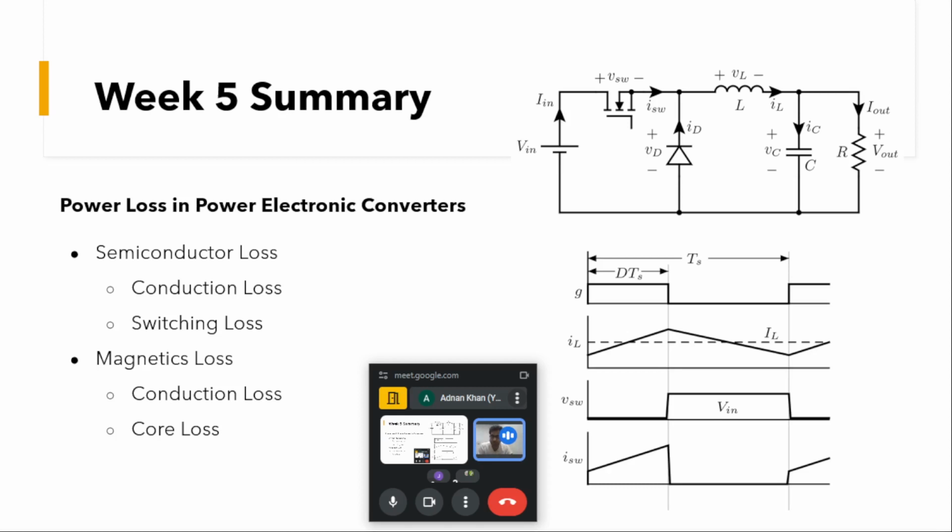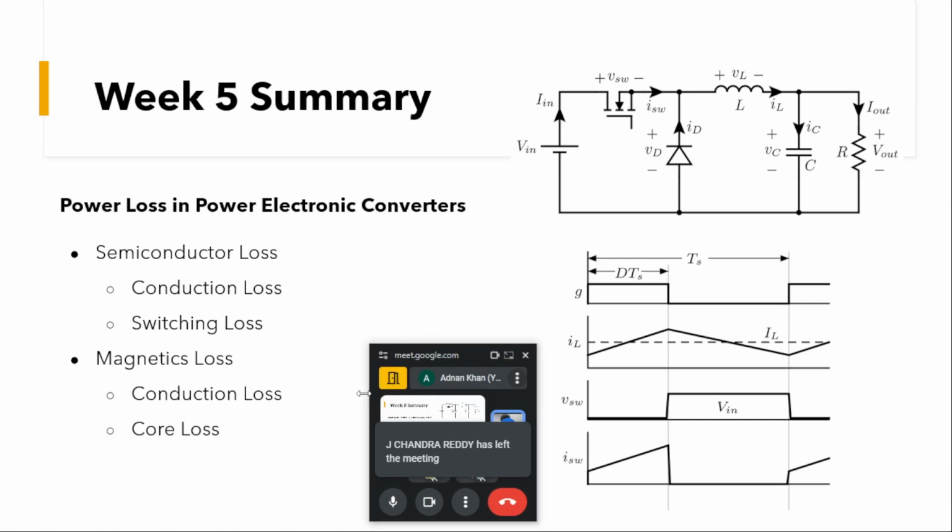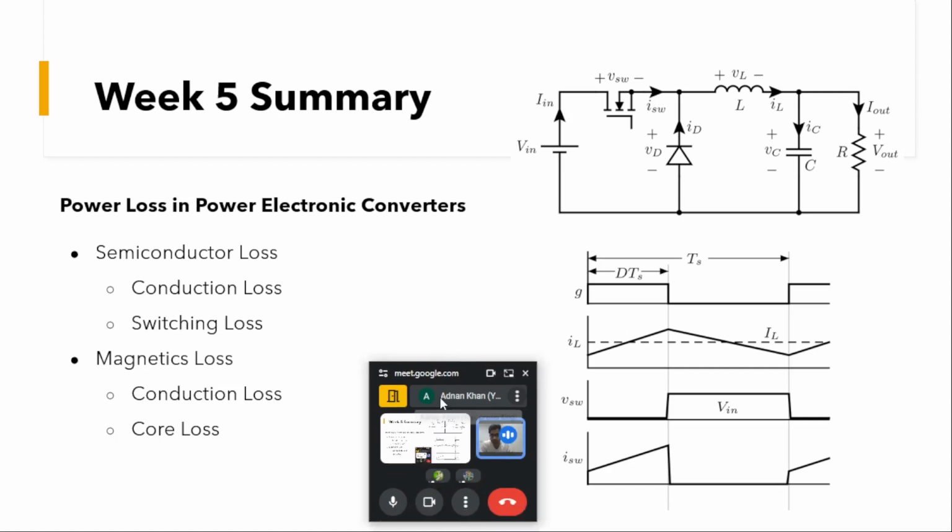as well. And besides this, as we know, to have some inductance we wound the coil on a particular core, which may be a ferrite or a sendust or some other core, and there will be some losses associated with the core as well, because of the change in the flux, and so on and so forth. These losses come under the section of magnetic losses associated with devices.